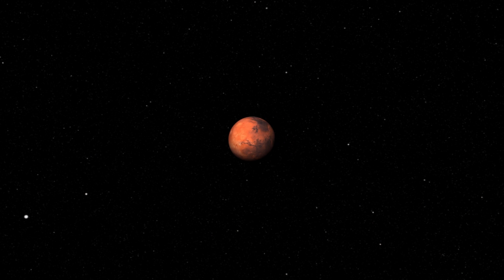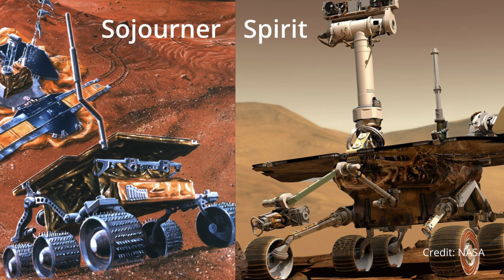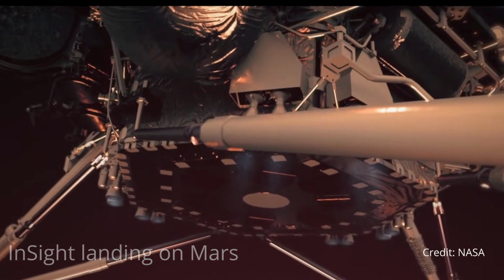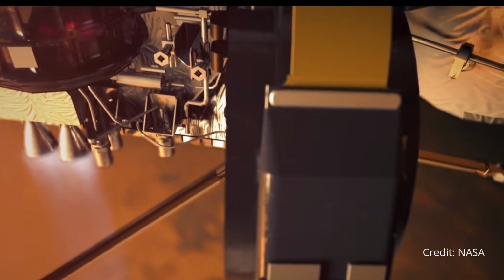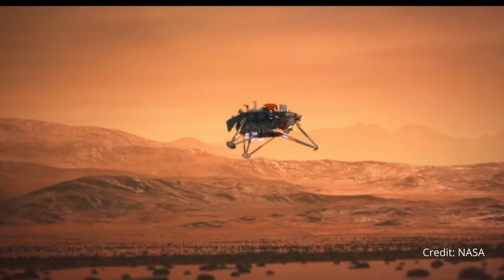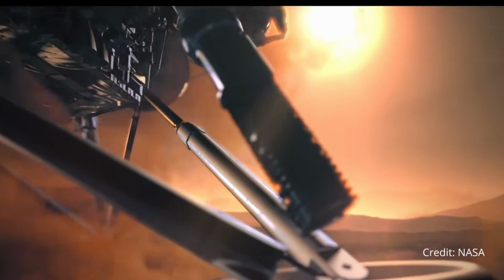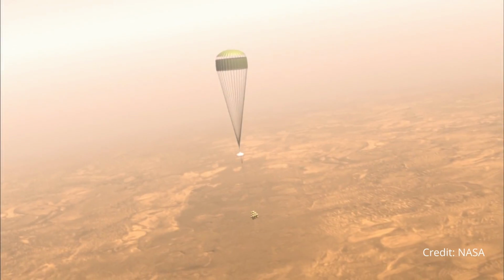This landing system that was just described was used on the Mars Pathfinder, Mars Exploration Rover A, and Mars Exploration Rover B missions, but it's not necessarily required for landing on a celestial body with an atmosphere. NASA only used this method because it's a low-cost alternative to using a precision landing system that uses a parachute retro rocket system where the retro rocket takes the payload all the way to the ground. Such a system requires a rocket system that can be throttled and cut off on command. It also requires measuring the distance to the ground accurately. The landing system used on the Mars exploration rovers lacked both of these capabilities.